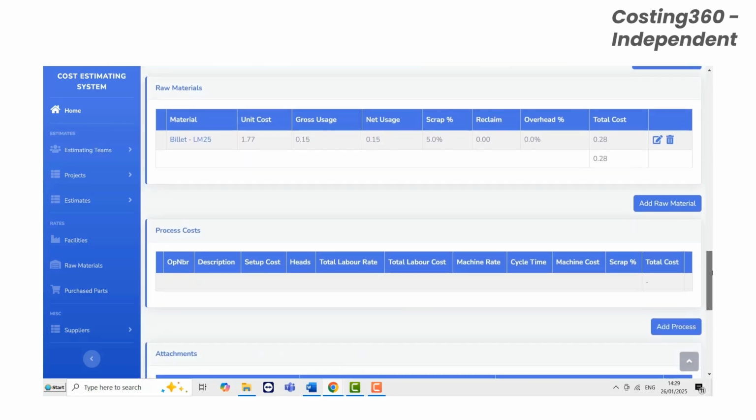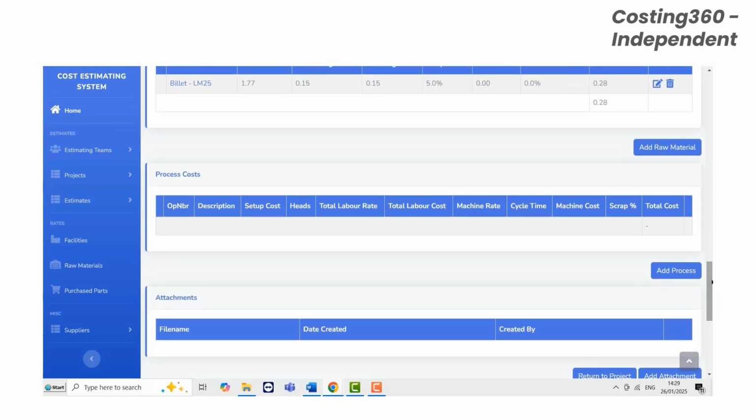Let us now consider the manufacturing process. From inspection of the component, we have concluded that this component is manufactured using pressure die casting. There are two aspects of this process, which we need to understand. What size die casting machine do we need, and what is the manufacturing cycle time? In order to help us answer these questions, we use a side calculation.